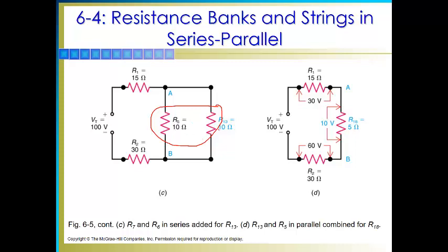These resistors are both 10 ohms, so we should get a resistor that is less than 10 ohms, and in our case it was 5 ohms. So we replace these two by one equivalent resistor that is 5 ohms. Now we have reduced our circuit to a simple loop that has 3 resistors in series.